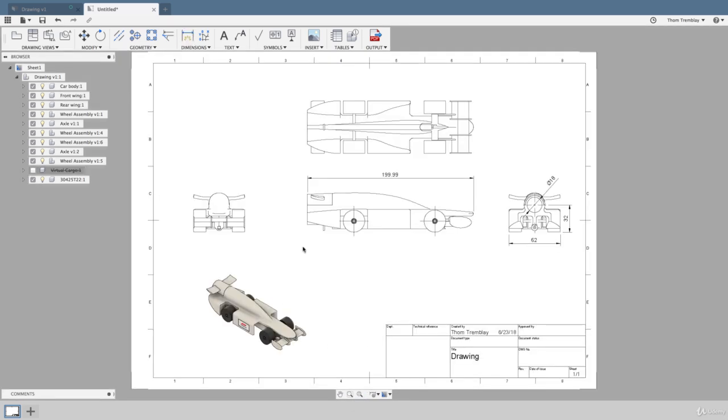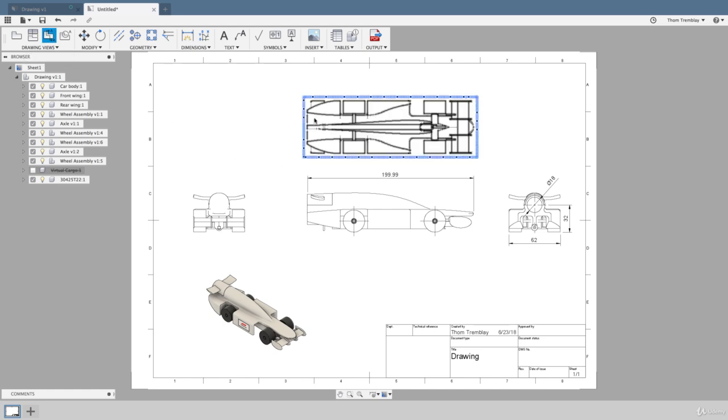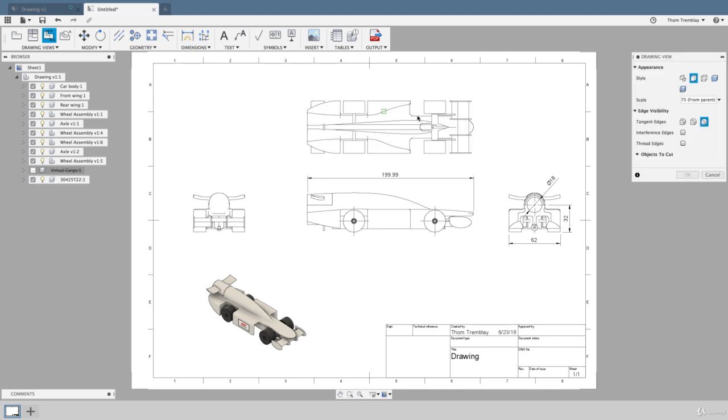We can also place section views by selecting a parent view. We're not going to place the section view directly on the center line of the model. Instead, we'll use a position that will allow it to section through the body at the thinnest point so we can understand what the contour of the body is as it transitions through this section plane. Setting where the section line will begin and where it will end. Then, using Continue to place the view.